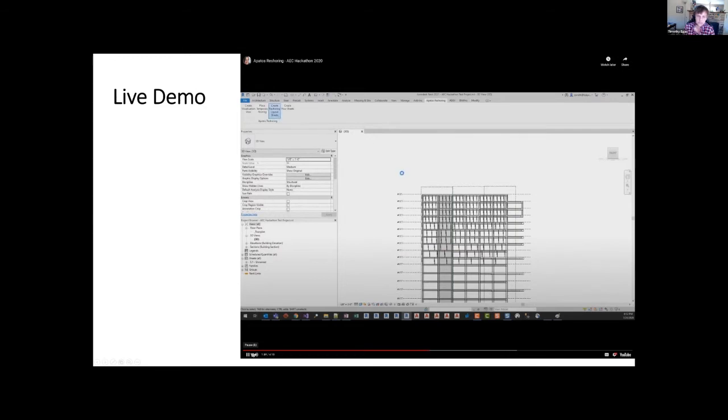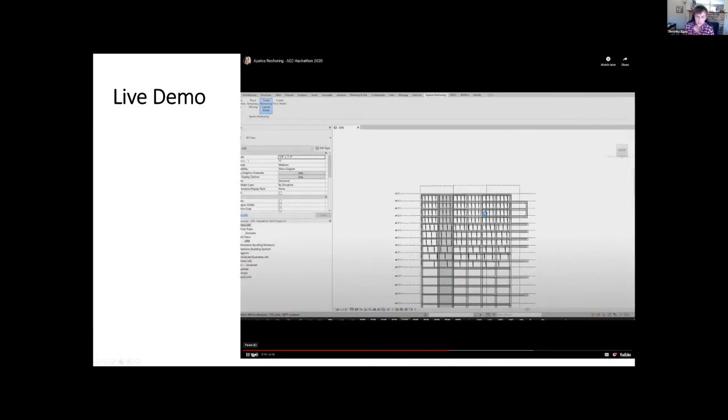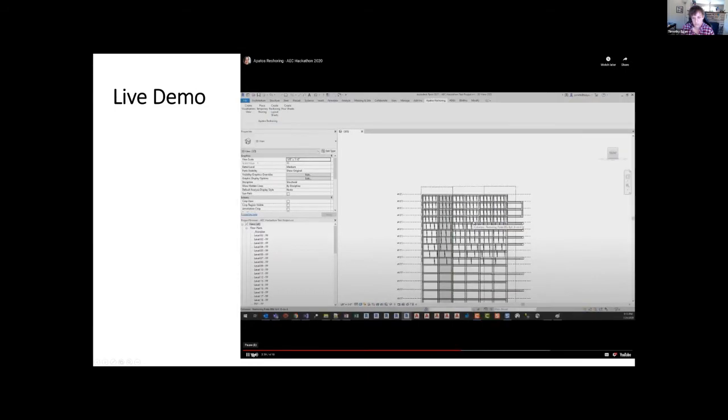Create reshoring layout sheets will generate full floor plate sheets. They will contain the reshoring members that we've placed programmatically. They will dimension from center to center of those reshoring members. They will include two schedules, one of the level, which will indicate the loads on that level, and another of the reshore columns.